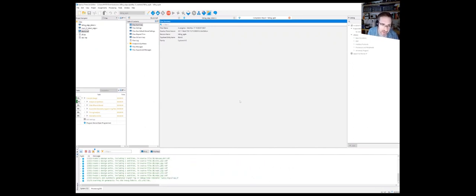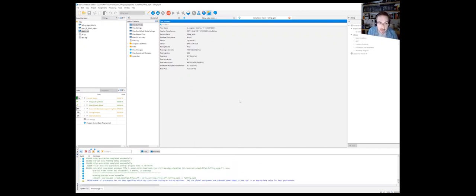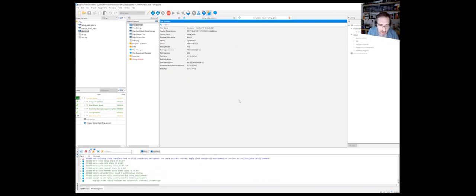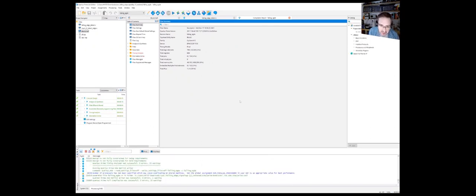So what I'm looking for with this more robust design with the synchronizer stages is reliability of the width of that trigger pulse. And ideally, we want that to be one full clock period, because that gives us the best chance upstream of capturing that signal if we use an always at negative edge of clock block. It gives us the greatest amount of grace either way, and it might not make that much of a difference in a very simple design like this, but when you have a complex design, things like this do make a difference, especially in high speed designs.